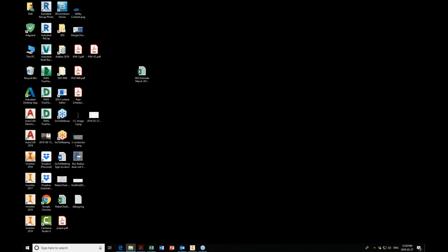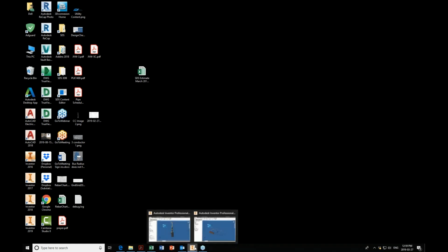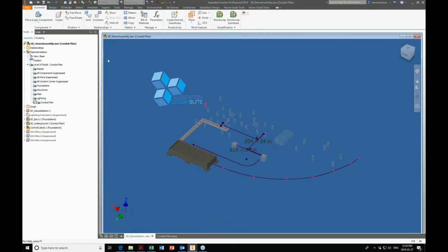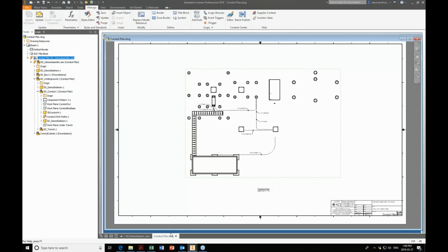Okay, when you annotated the drawing 1-2 conduit, why did you have to type this info? Seems like the information is affiliated with the part. Because we are projecting the line, we're only identifying that line, so we're not actually identifying the conduit part. We can identify the part with a leader in Inventor, but it's got to be the part. So when we came in here, we had that plan view open.